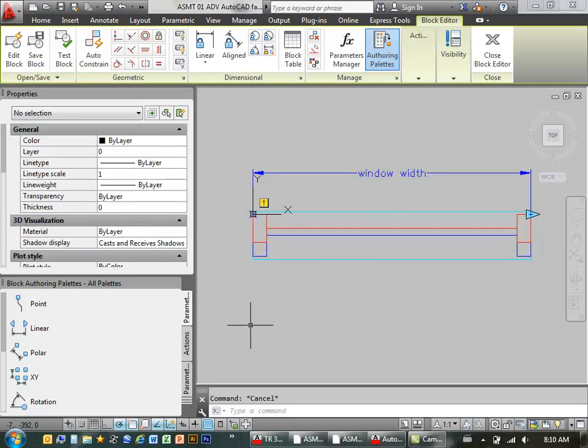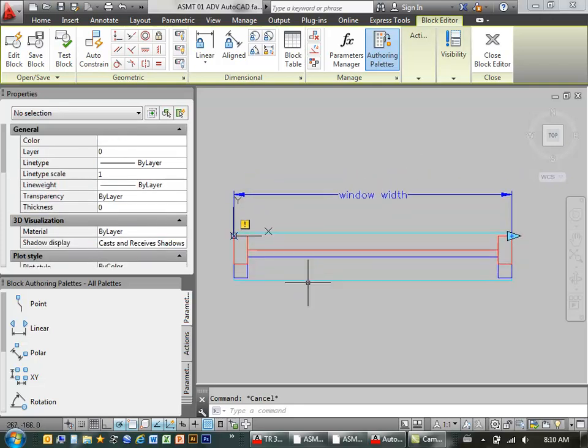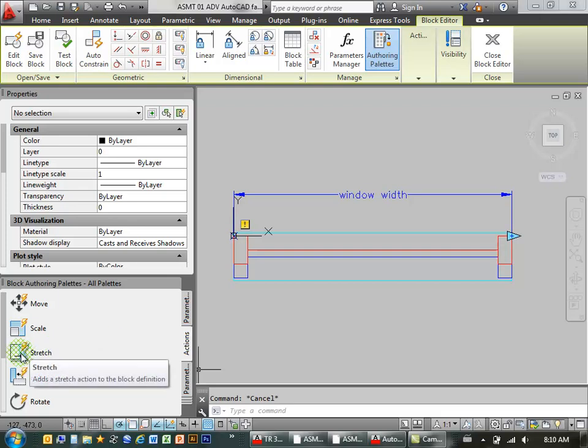Okay, now that parameter is all set up. What's the next step once I set a parameter up? Yeah, so then always action follows the parameter, so I click on the action, and with this one I'm just going for a stretch, and there's no angle offsets or overrides to worry about. So this one's pretty straightforward.